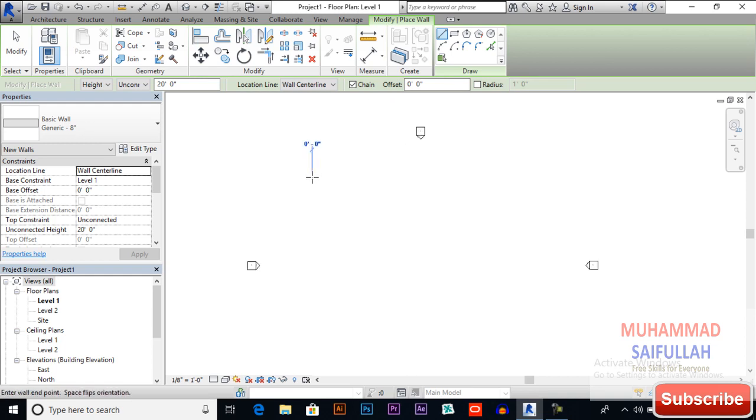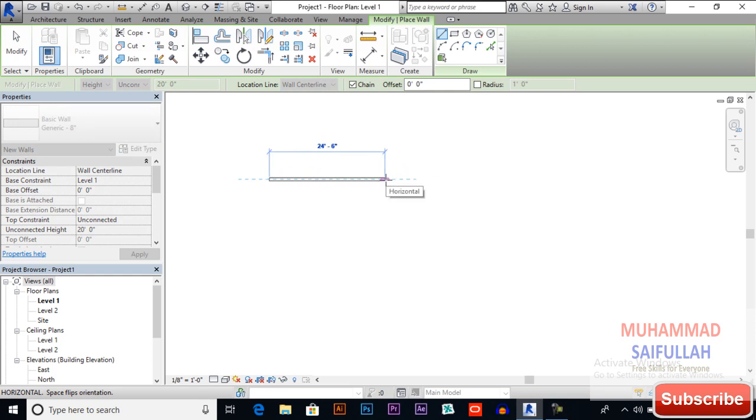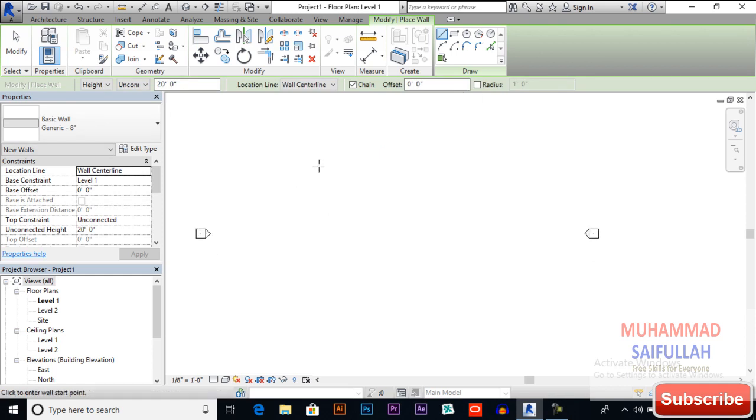If you see, if I'm drawing, I can only draw a wall straight as a line. So I want to change my wall setting. For example, I want my wall in a rectangle shape, like we draw a rectangle in AutoCAD or any CAD software. So here I will select from line to rectangle. Let's draw.